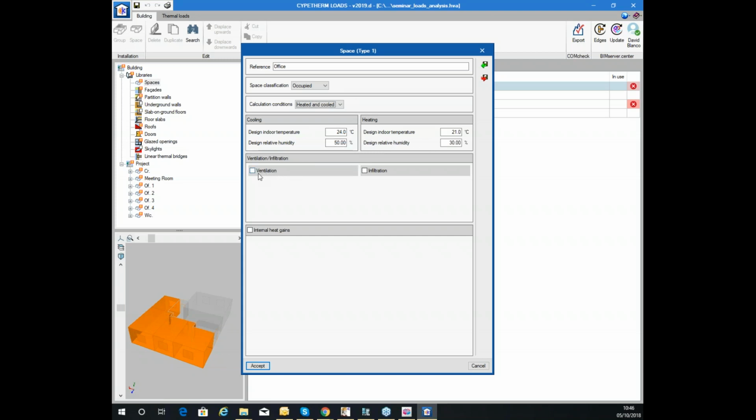Okay, I'm going to leave it by default. And all the internal gains for ventilation. Ventilation is divided into pure ventilation or infiltration, if you want to consider infiltration according to that method or whatever. And the internal heat gains for occupancy, lighting, and other equipment, or miscellaneous or extra loads, or extra gains. For example, ventilation, let's see, for air changes per hour, you can work with different units. For example, air changes per hour, let's see, 1.2.